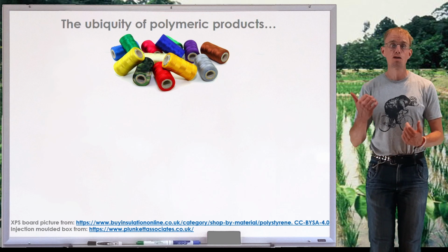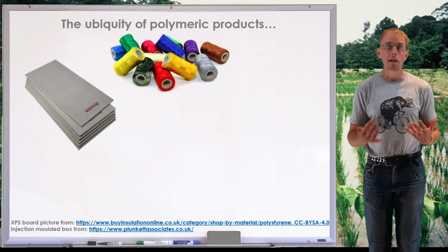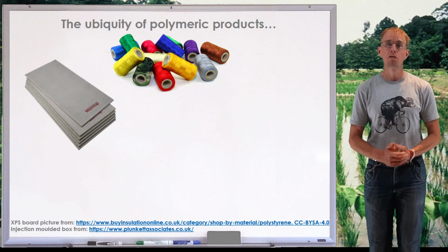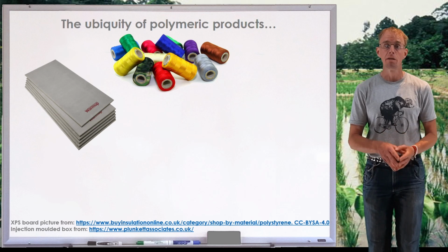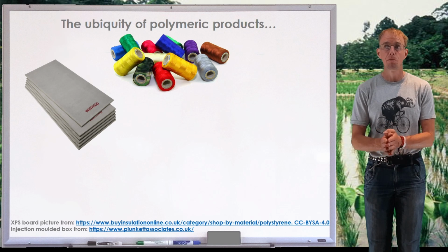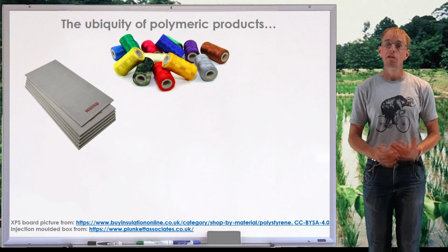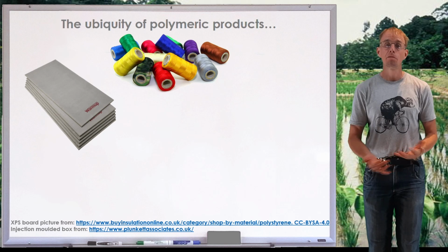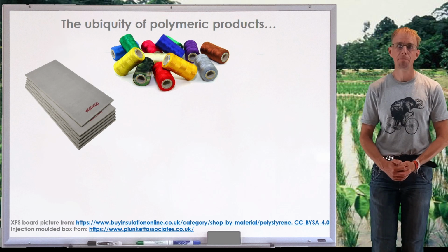We can also look into the construction industry, for example, and thermal insulation. Many environmental standards these days require a minimum insulation specification, and you will find that one of the means that this can be fulfilled is through insulated board put between, say, a suspended ceiling and the outer skin of the ceiling. Some of these insulated boards would be, for example, expanded polystyrene, again, a product of the polymer processing industry.